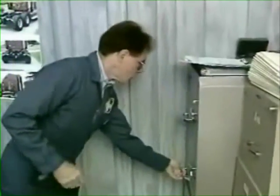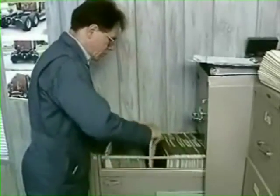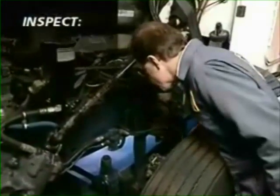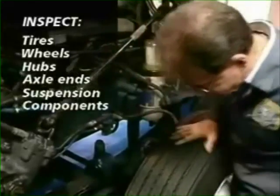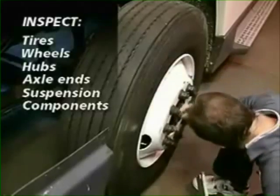The next step is to review the vehicle's maintenance history to see if any recent action occurred prior to the vibration complaint, or what has been done since the vibration was first identified. The third step is an inspection of the vehicle, including tires, wheels, hubs, axle ends, and suspension components to determine if any irregularities are contributing to the vibration. The last step is to go for a test drive in the vehicle with the driver to duplicate the sensations the driver is feeling under operating conditions.